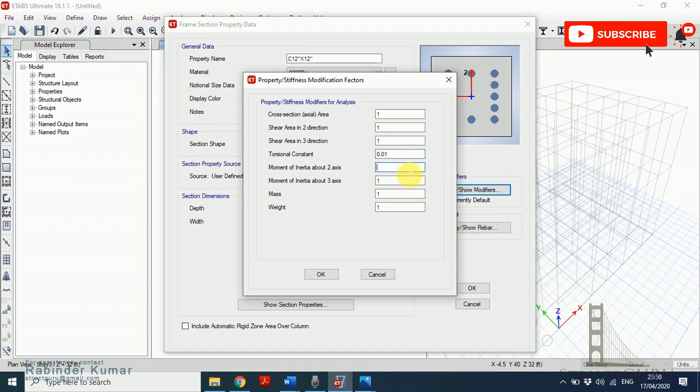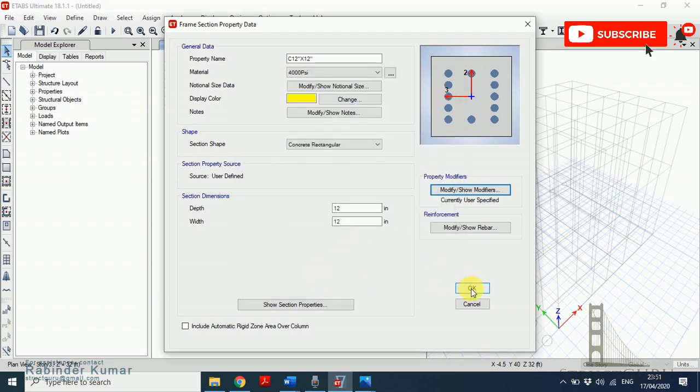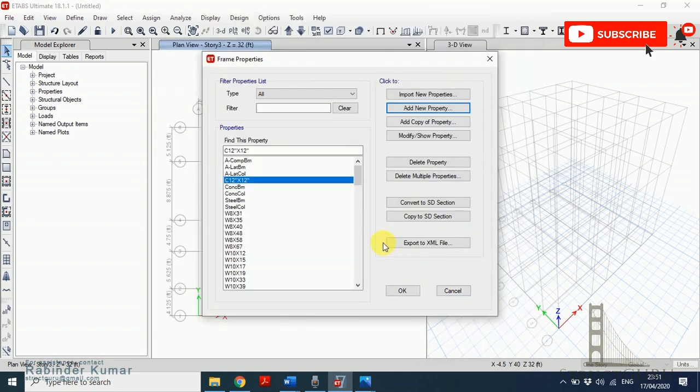For moment of inertia about 2-2 axis for a column it is 0.70, and moment of inertia about 3-3 axis for a column is 0.70. After modifying these values, click OK. Click OK. So we have successfully defined the column.